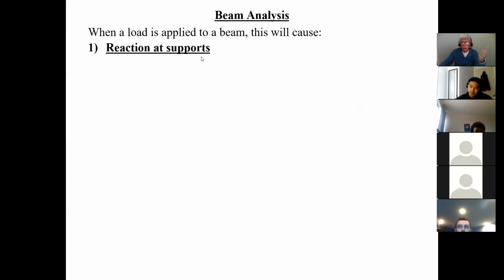So in other words, the first thing you do is I have a beam and I have reaction areas. The first thing I need to do is calculate the reactions at the supports, because once I calculate the reactions, I can go and calculate the other forces or internal forces that the beam might be subjected to. So I calculate reactions at the supports. And I think you guys, without realizing, that's what you were doing. In other words, the teacher gave you a beam, he put all kinds of loads on it, and it says, calculate the reactions, calculate the shear, calculate the moments. And I don't know how well they explained that, but I will give you an appreciation of what you're actually doing, okay? So reactions at the supports.